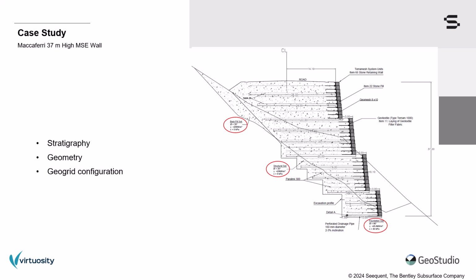Construction commenced with the placement of the gabion system. Each gabion had a height and a width of 1 and 2 meters respectively. The steel wire mesh extends to the back of the face of the wall. A structural soil was placed behind the wall up to the grade of the top of the gabion.